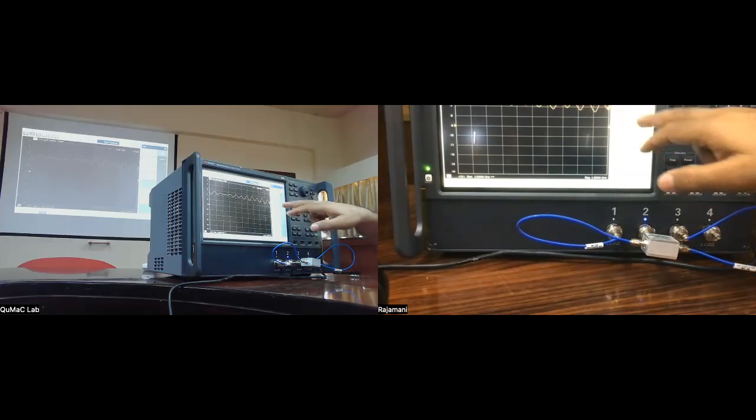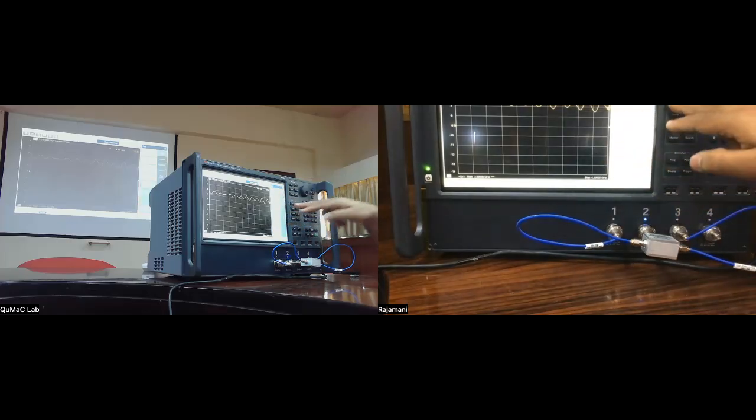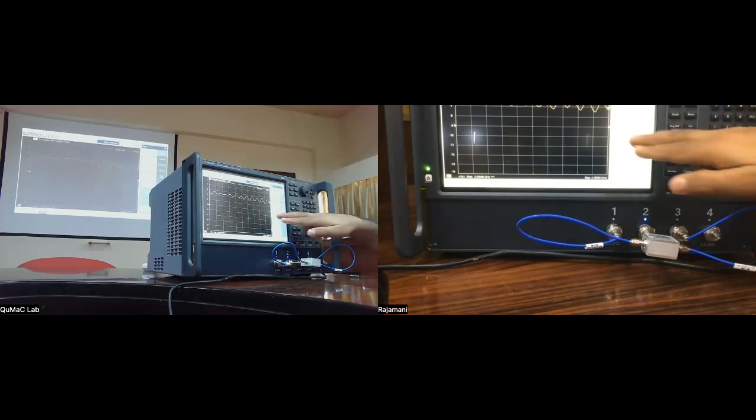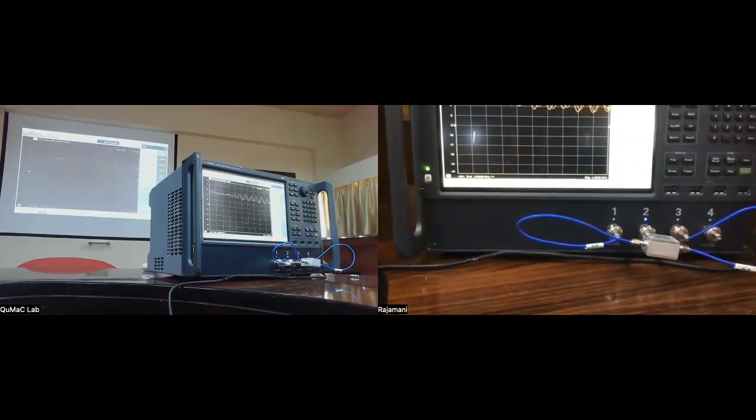So now let's put this to memory and look at the other one. That is going to be S32. Mostly the same, again with a slight shift in these frequency patterns, but it's also -6 dB. So remember, 3 dB is a factor of 2, 6 dB is another factor of 2, a factor of 4. So 1/4 comes out of one port, 1/4 comes out of the other port, and the rest, the 1/2, dissipates inside the device itself.